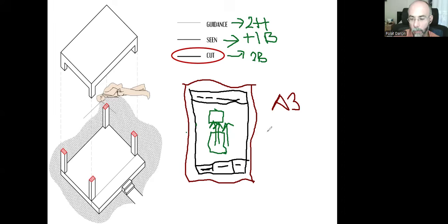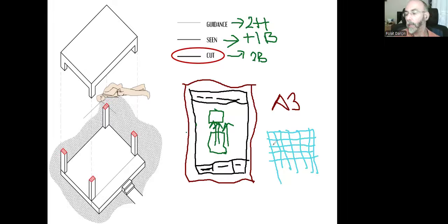And if you prefer a normal squared paper, not a white paper, something like this. The squared paper has squares, and these are already created guidelines for us. And not a millimetrical paper, but a normal square paper. Each one of these squares is approximately half centimeter, and you can have two of them for 1 centimeter, so that by using these grid lines, you can have a scaled freehand drawing.